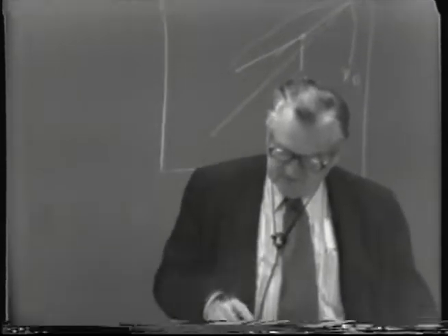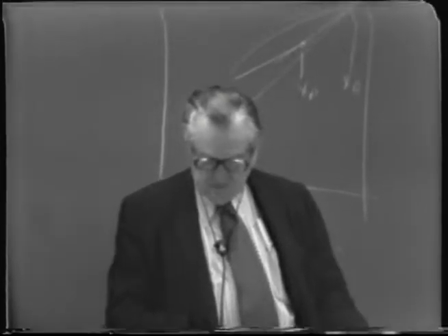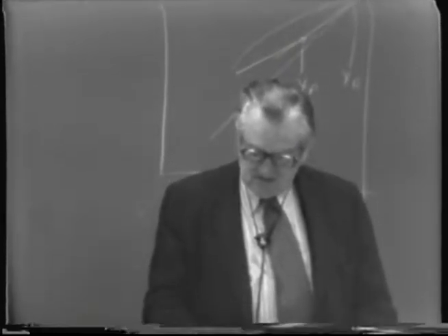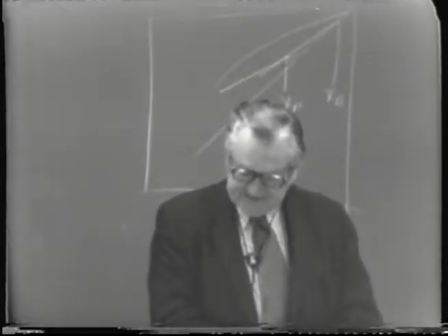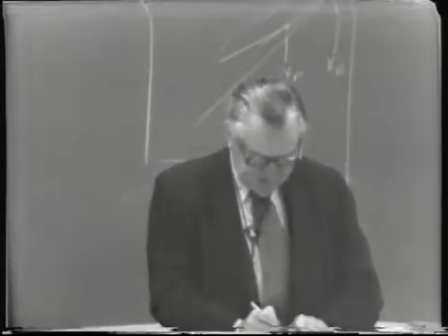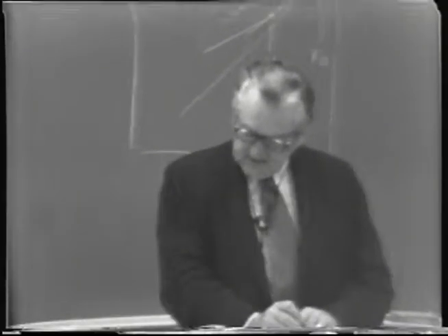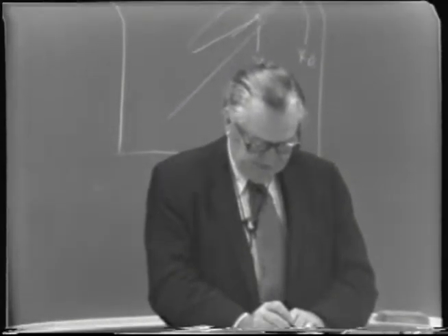So now, referring back to the diagram, translating that into a mole percent, it comes out to be about 37 mole percent. And this mole percent would be attained between the 11th and 12th plates from the top.